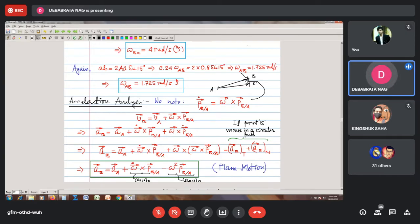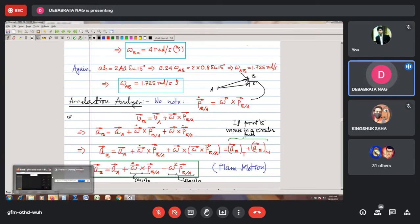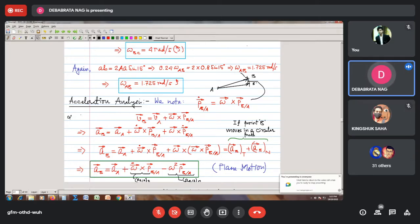Now omega bar dot, as I was telling the other day, since we are dealing with a plane motion, is actually the angular acceleration of the body. So this is the angular acceleration, and how will the angular acceleration be found? Since your body is executing plane motion, the direction of angular velocity always remains the same. The only thing that changes is its scalar magnitude.